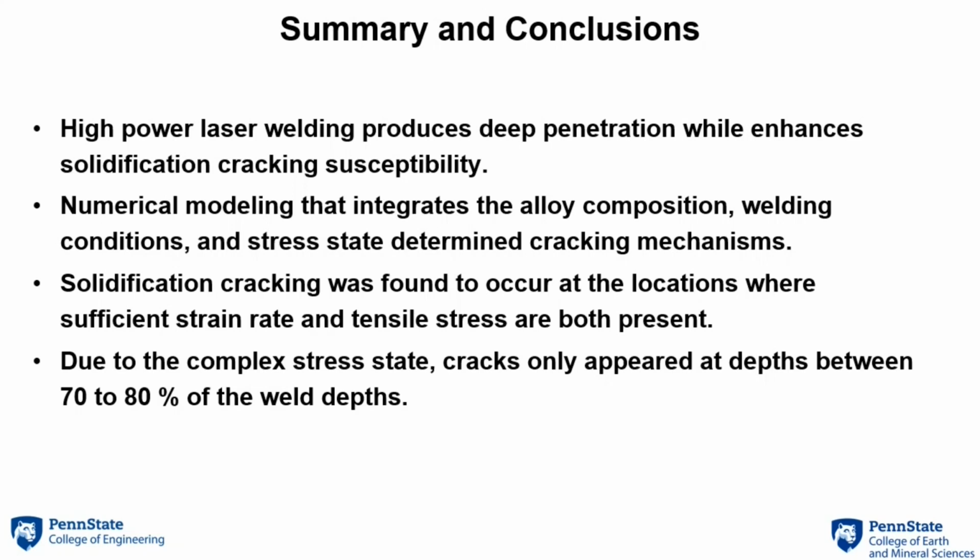to determine the cracking mechanisms. And using this model, it has been confirmed that solidification cracking can only occur at locations where we have both tensile stress and sufficiently high strain rate. And because of this complex stress state, cracks only appeared at depths between 70 to 80% of the weld depth.